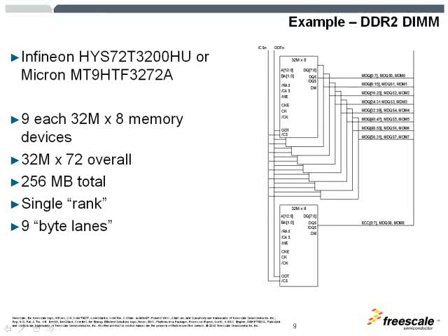As you can see, all the address and command buses are connected to all the SDRAMs to the same locations. The only thing that is different between the connections for these SDRAMs is the byte lanes. The order of the byte lanes, as you can see, is different.